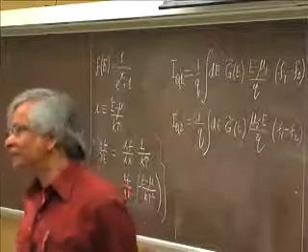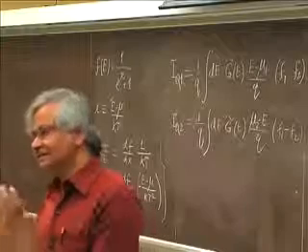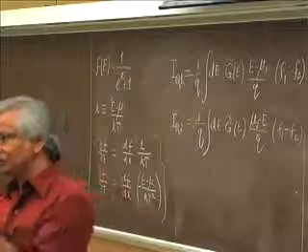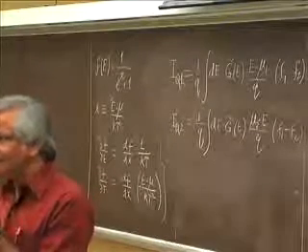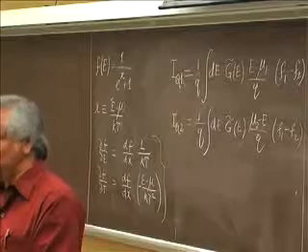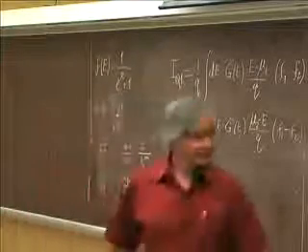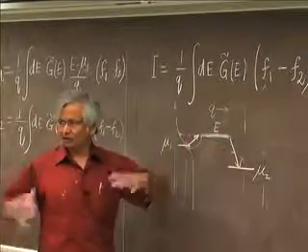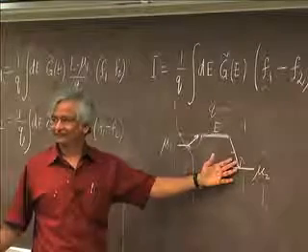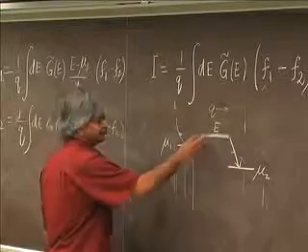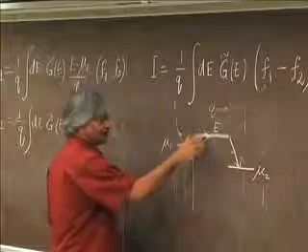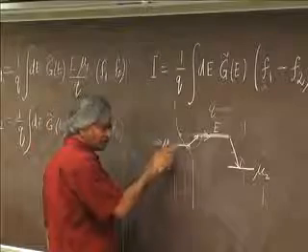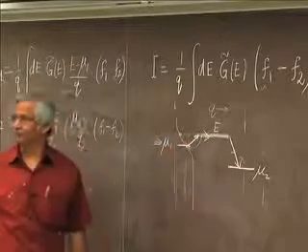Right. Usually, this is why I say that this elastic resistor concept helps say all those things a little more clearly, because usually when you think of a long device, it is harder to understand what mu means and all that. Whereas here what we are saying is, think of this channel connected to two contacts, and the contacts are big things, so the mu's are well-defined. And so you take this electron at this energy, but then when electrons come into the contact, they come in at mu. So they kind of have to absorb all this energy from this contact in order to rise up in the long run.